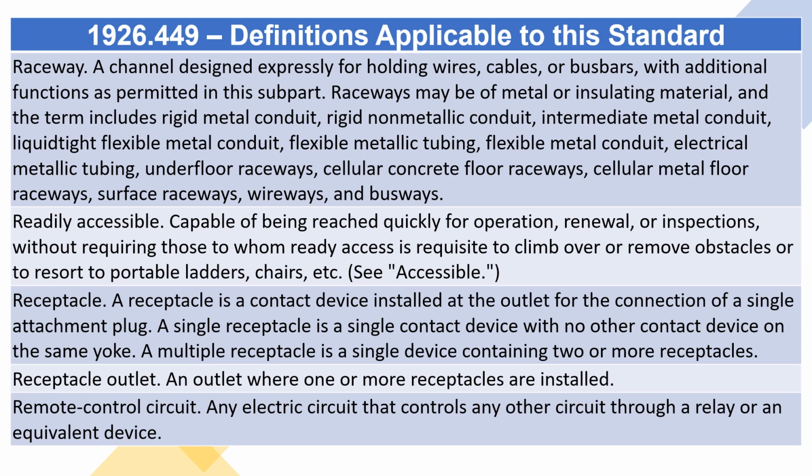Receptacle. A receptacle is a contact device installed at the outlet for the connection of a single attachment plug. A single receptacle is a single contact device with no other contact device on the same yoke. A multiple receptacle is a single device containing two or more receptacles. Receptacle outlet. An outlet where one or more receptacles are installed.